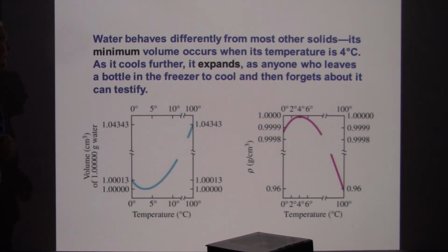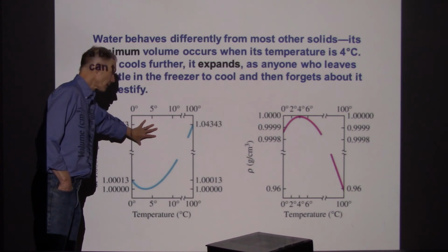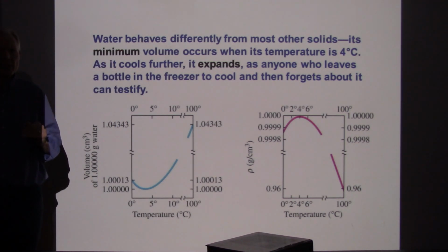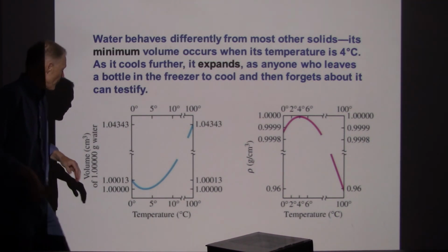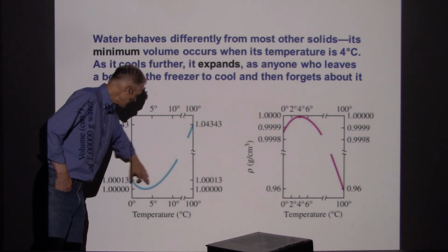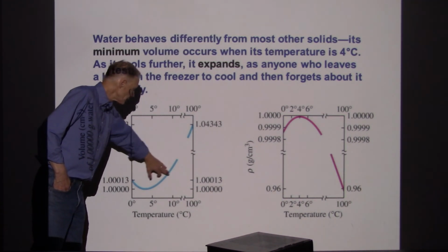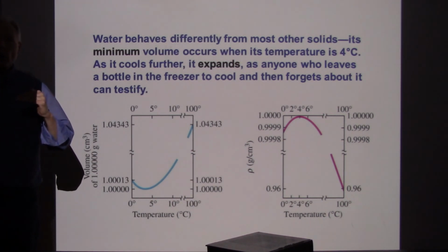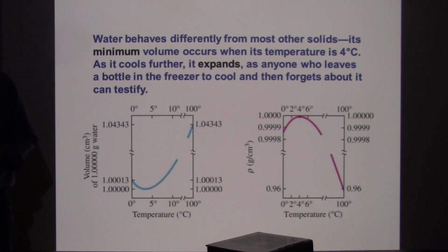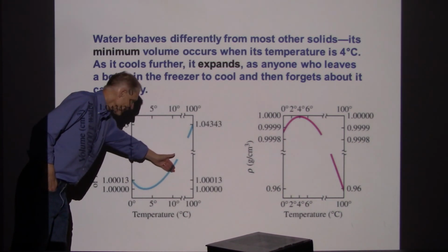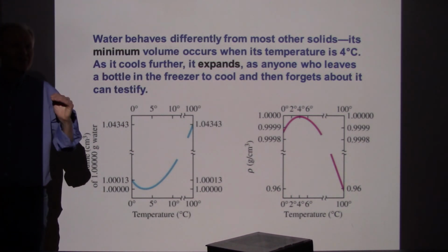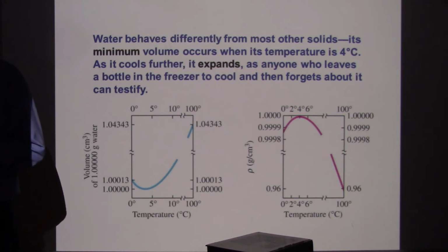One thing to keep in mind here is, I think there's some homework problems to look at this. Water's expansion is complicated. It's not well represented by a linear function at familiar everyday temperatures, especially when we get down into the range between 0 and 10 Celsius, which is pretty common. Remember, as you get closer and closer to 0, water actually begins to expand. And once it turns to ice, it expands even more. So water's density, it's not linear. It's a more complicated function. Just something to be aware of.